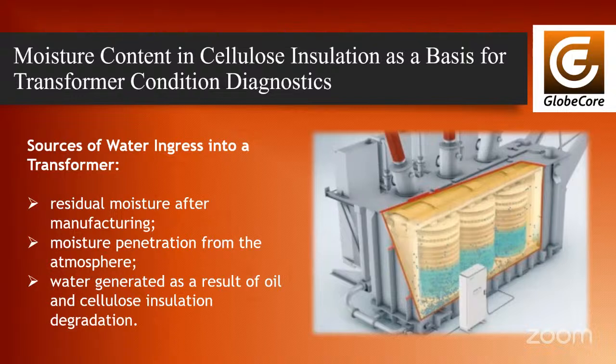Second, moisture from the air. This happens when radiators, bushings, or expansion tanks are installed after transport or during repairs without using dry air. It can also happen if the air dryer is not replaced on time.